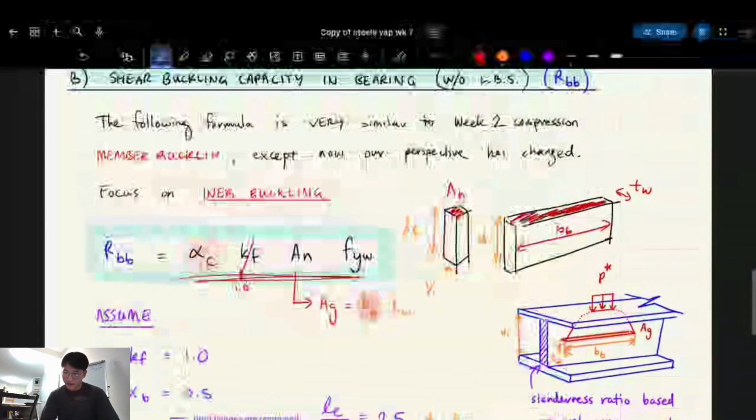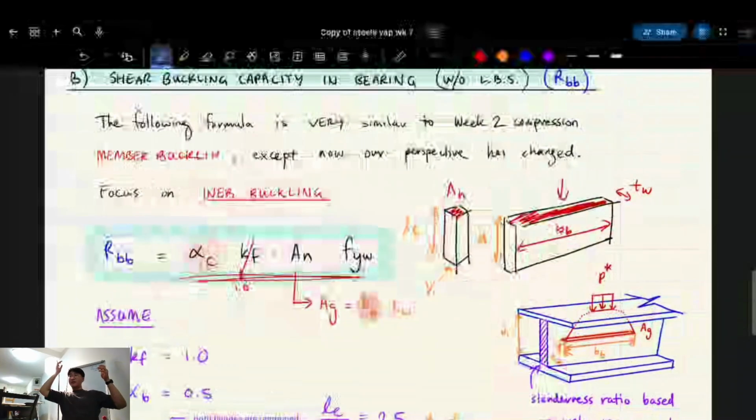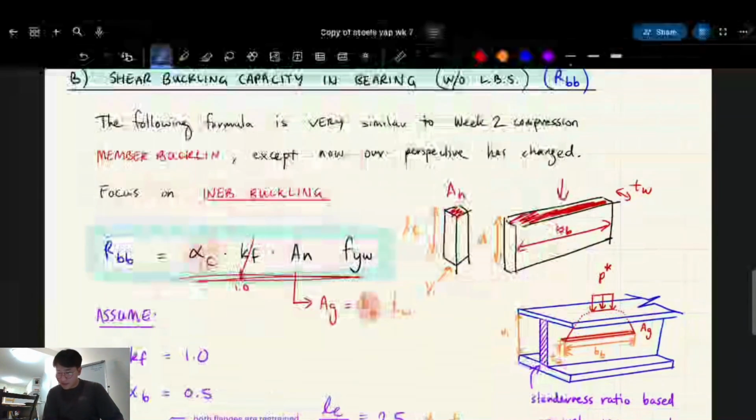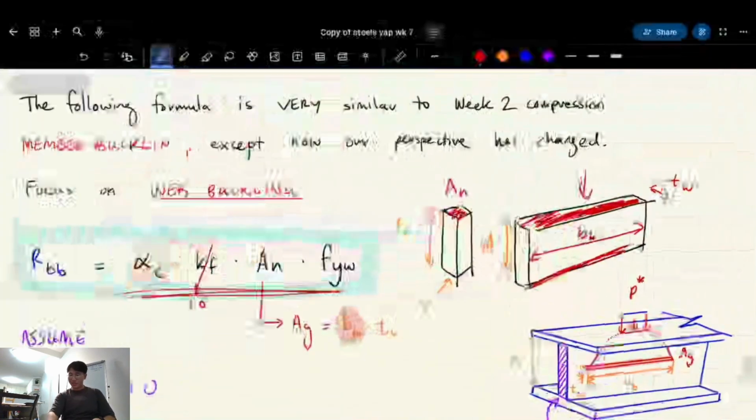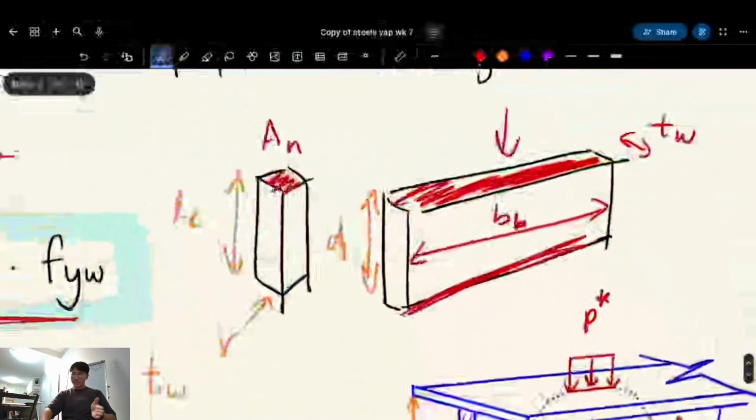Yeah, and so BB is important because you know how we had to find all those things that increase the bearing width and spread it because it goes through the flange, through to the middle of the web. BB is what that width has become at the middle of the web. And then we just treat that like a column and do a buckling check. Just based on that shape that I drew here, where do you think the minor axis is?